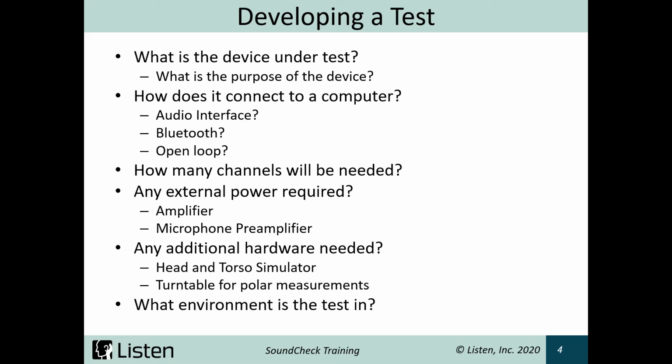If that's the case, as you're developing your sequence, it's good to think about how the logic will interface with those pieces of hardware. If you're going to have logic loops because you'll be using a digital I/O, you'll want to think of that from the development stage. You don't want to write out a full test, then have to go back and add in a bunch of things that you weren't thinking about at the start of it.